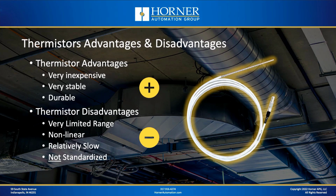Okay, what are the advantages and disadvantages of thermistors? Well, they're very inexpensive, they're very stable, and they're durable. So those are significant advantages. And as you can imagine, in HVAC type applications and building automation type applications, inexpensiveness is important. And the biggest disadvantage of a thermistor, namely a very limited temperature range, is not such an issue with building automation because you're generally measuring ambient type temperatures over a pretty narrow range.